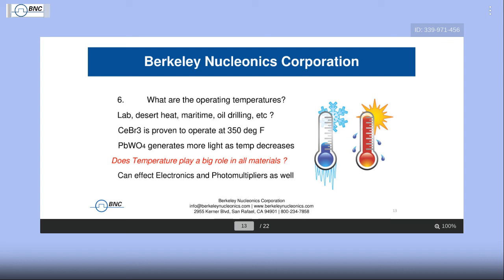All of these things come into play. The photomultiplier tubes, very large analog devices, are greatly affected by time and temperature, and particularly temperature. Their center point will drift, and they call it drift. As the temperature goes up, it'll drift a little high. As the temperature goes down, it'll drift a little low on the gamma ray spectrum.